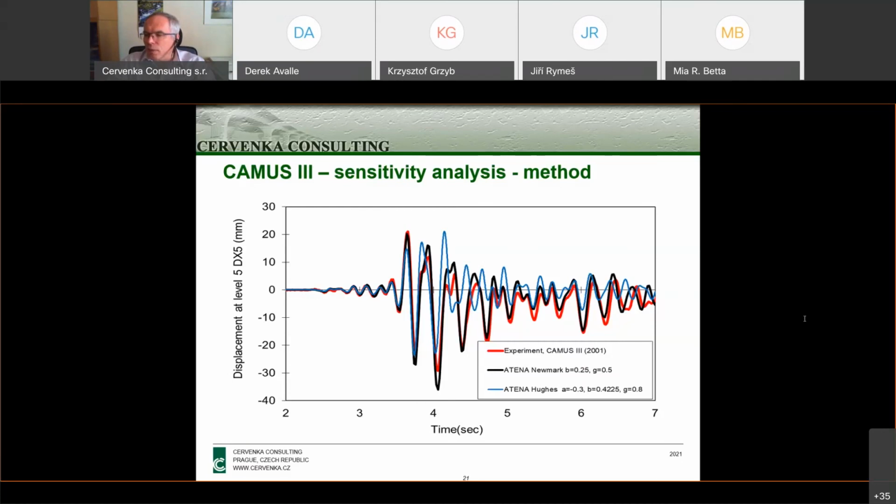So for instance, you can make a seismic analysis in ATENA. This calculates the damages, and then you can load such a structure after that to evaluate its strength based on the damages. Otherwise, the damages can be introduced, for instance, by reducing the material parameters like tensile strength in the damaged areas. That's, let's say, the best way to do that. Or we can also introduce some interfaces to simulate some pre-existing cracks.